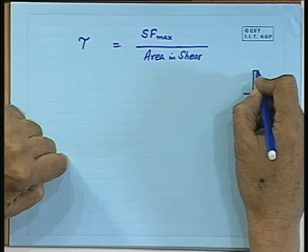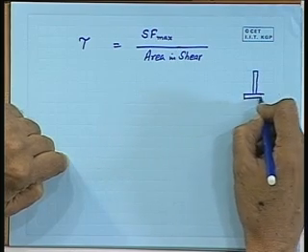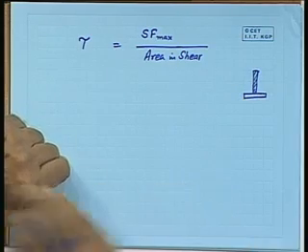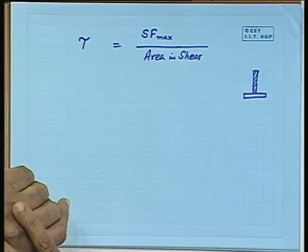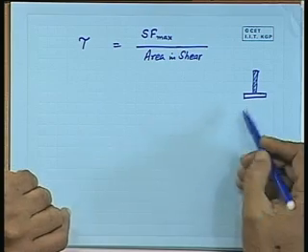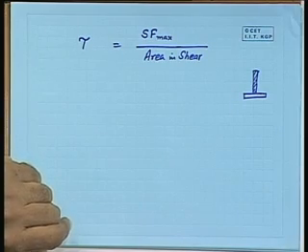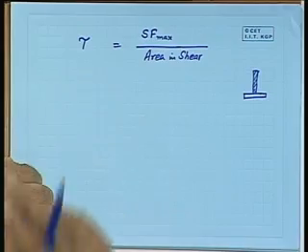So, that means when we take a particular cross section, then wherever we have the webs, suppose you are having a longitudinal there in the form of a T section, then it is this vertical member of the web which will participate in taking the shear load, not the flange of this. Okay. And therefore, we will try to find out now that shear stress is position dependent within the section.